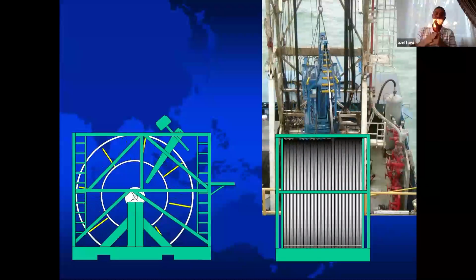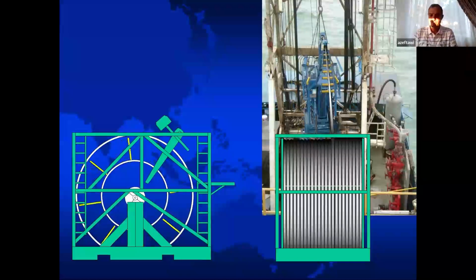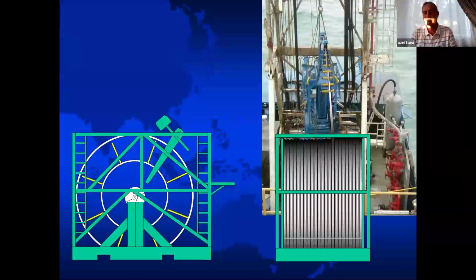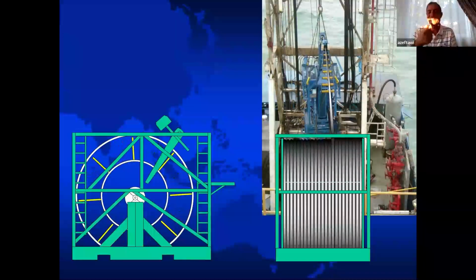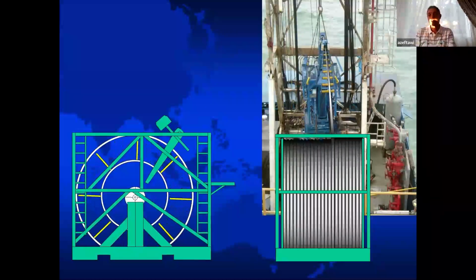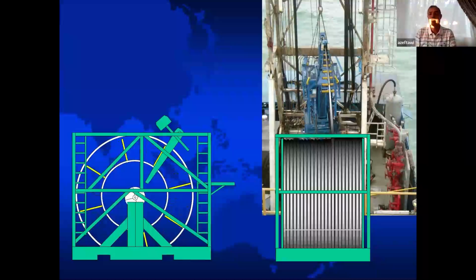What's beneath the roller is the shaft, the roller shaft. Then you start having friction between the pipe and the roller shaft. Who wins? The shaft. Its material is harder than the pipe, so it starts eating your pipe. So these rollers, if you didn't maintain them well, will affect your pipe life.